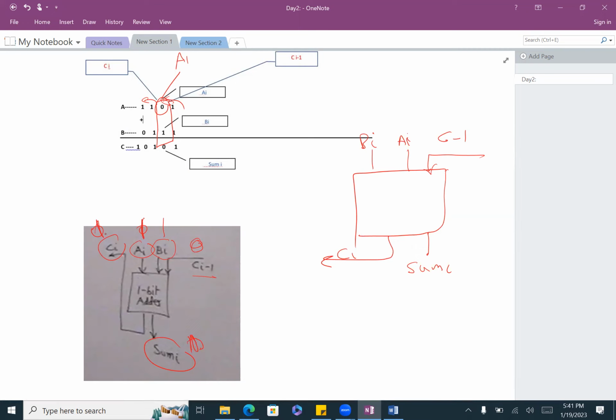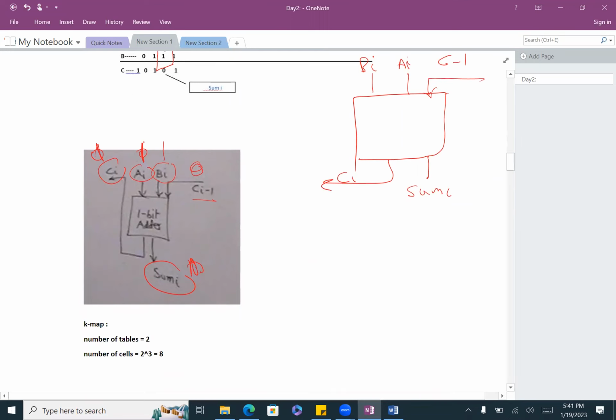We slice our problem into an n-bit approach, and we do the design for only 1 bit. Then after you do the design for 1 bit, you can replicate that. If you want to do a 4-bit adder, you replicate this circuit 4 times, then somehow we connect them together. We'll see how we connect the links together. Are there any questions so far?